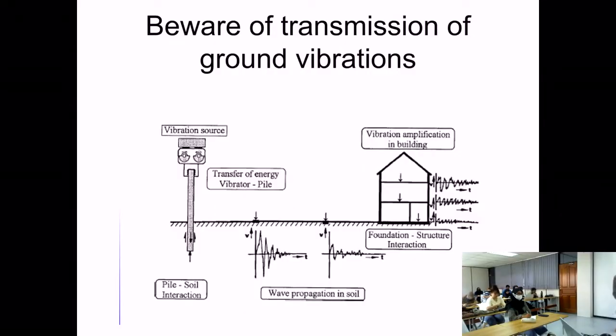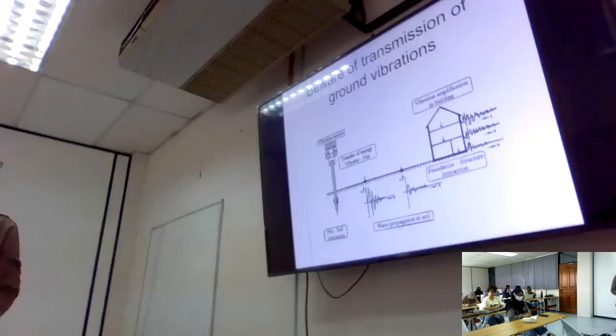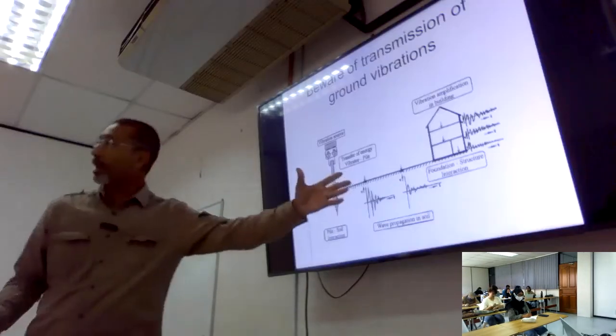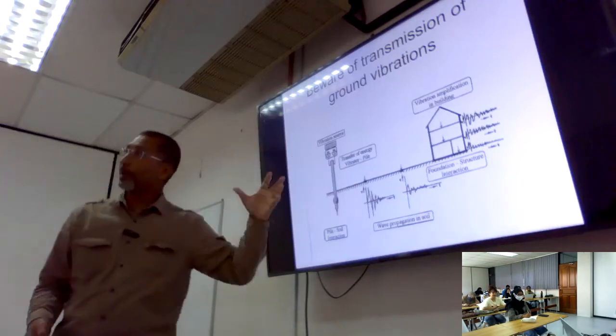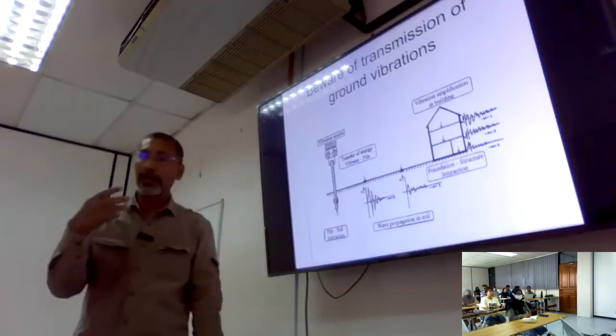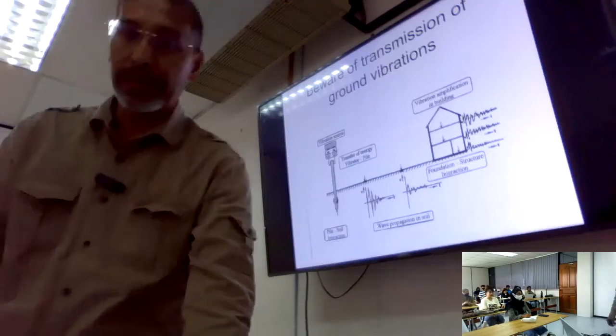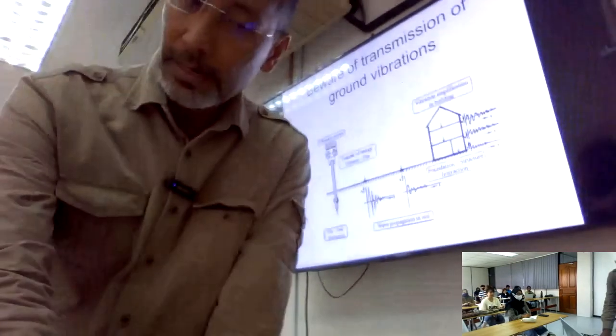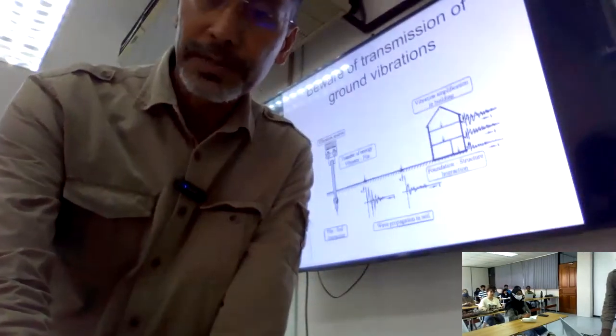Of course, these are some of the things that you need to include in your costing. If you do costing, how to prevent excessive vibration and sound to nearby buildings. That's why I mentioned if you are doing the work in Penang, definitely the earthwork by law requires all this precaution system to be installed.